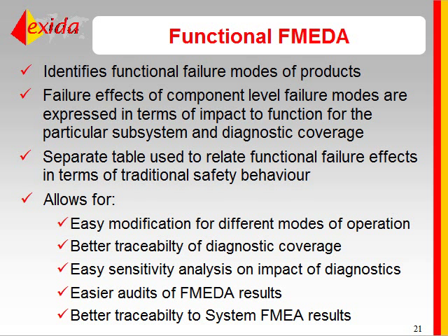And so one particular failure mode of a diaphragm might be large leak or heavy leakage, and the failure mode is valve or actuator moves to safe position or to resting position. That would be a functional failure mode of the actuator. Whether that's fail-safe or fail-dangerous depends on the application, of course, and we'll save that discussion for a little later.